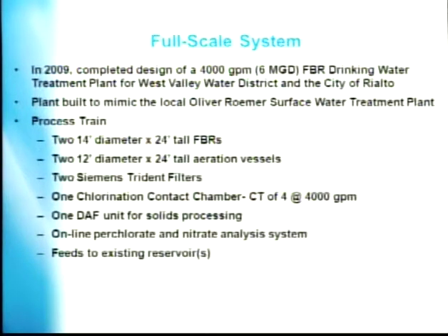Two Siemens Trident filters, and the question was earlier, what types of filtration can you possibly use? Well, there's continuously backwashing sand filters, there's multimedia filters, there's membranes. We went with this particular series of process technologies because this is what the operators had been utilizing at that surface water treatment plant. Again, we just wanted to mimic and try to minimize the stress on their operation.